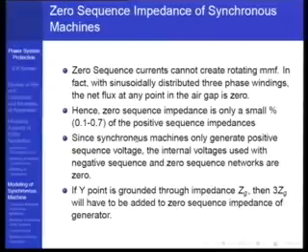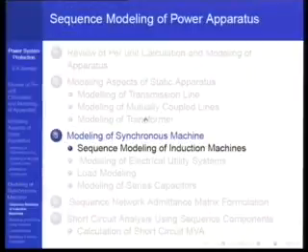But I presume that cylindrical rotor machines may have lesser zero sequence impedance, because the iron is uniformly available through and through. But here the iron is not uniformly available. So when you give zero sequence currents, the rotor is seen as a much more symmetric circuit if you have a cylindrical rotor. But the unsymmetric circuit is more seen with this, but you need to check it up.